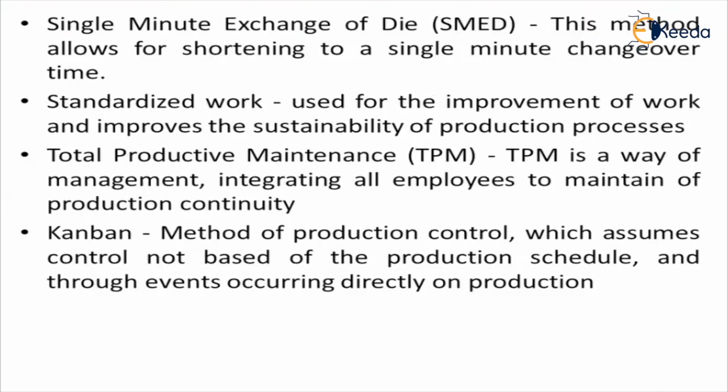Then single minute exchange of die. This method allows for shortening of changeover timing. It means that in a day, the changeover has to be done only one time. Say for example, in a CNC machine, in the morning we are going to load a program and keep it till evening. We are going to do the same thing, and only the next morning are we going to change it. We are not going to reprogram intermittently because it creates a lot of time wastage. So single minute exchange of die. Then standardization of the work.